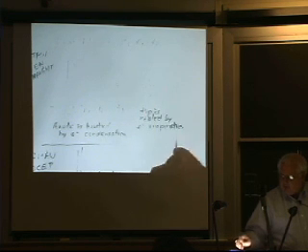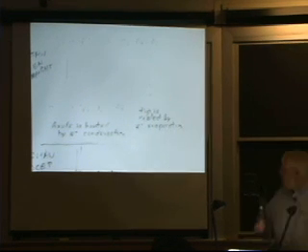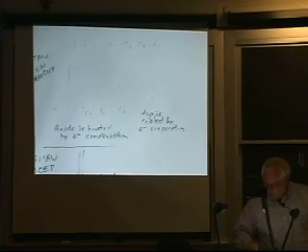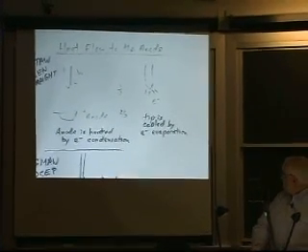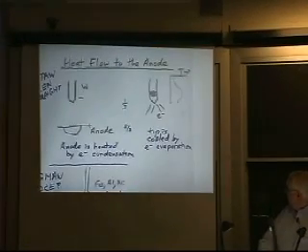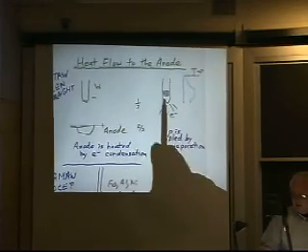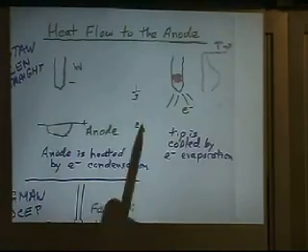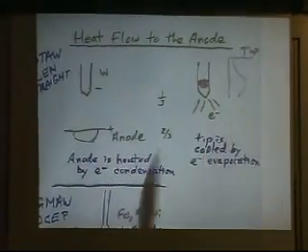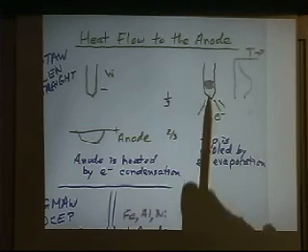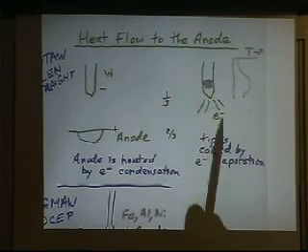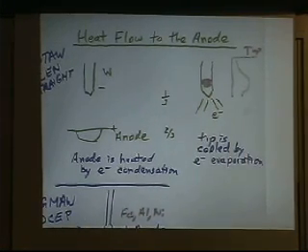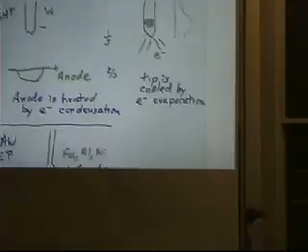that the hottest spot, if you plot the temperature, was right. Oops, sorry. This thing doesn't always like to stay where it was. Anyway, the hottest spot. So this is 1/3 and 2/3. Okay. So 1/3 goes to the cathode, 2/3 goes to the anode, and the hottest spot here actually is not at the tip. You get electron cooling, and in fact, I remember he used to explain that when you weld